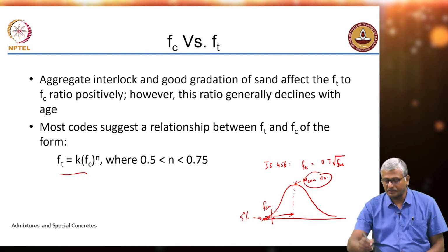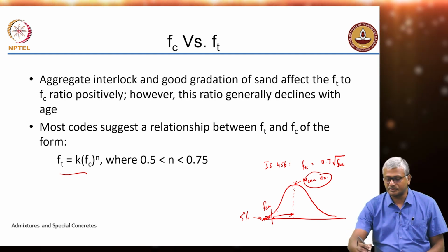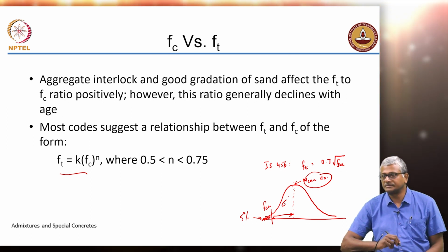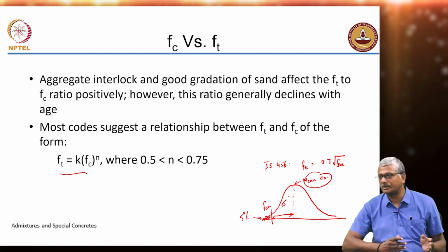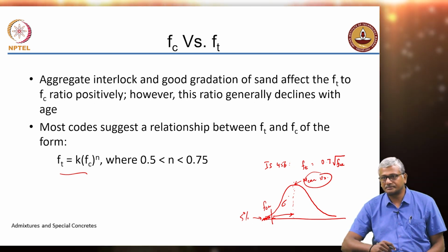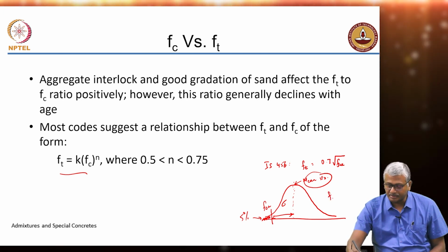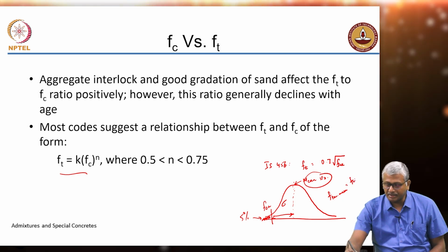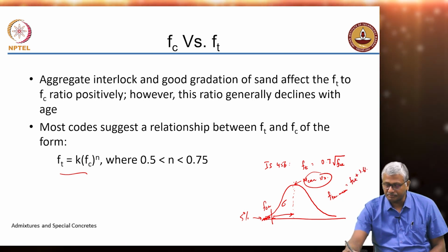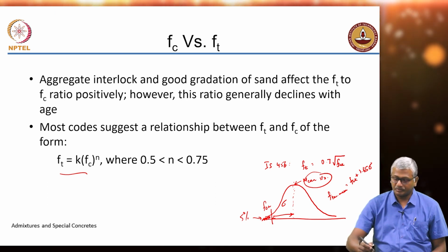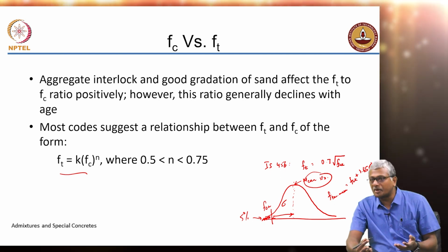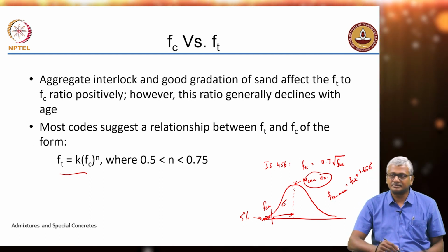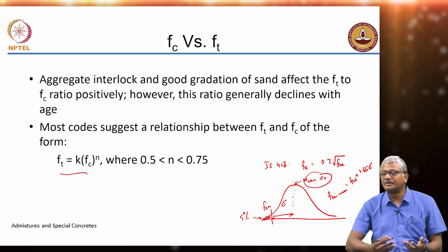How do you know that value? In a normal distribution, you know that because of the standard deviation, right? In a normal distribution, you can estimate the mean from the characteristic value with a standard deviation. So in this case, the mean strength is FCK plus 1.65 sigma in a perfectly normal distribution. Now there are obviously distributions that may not be normal, but for compressive strength, it's hard to imagine that you will have a skewed distribution,